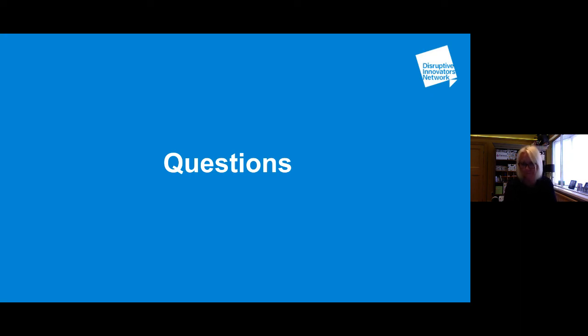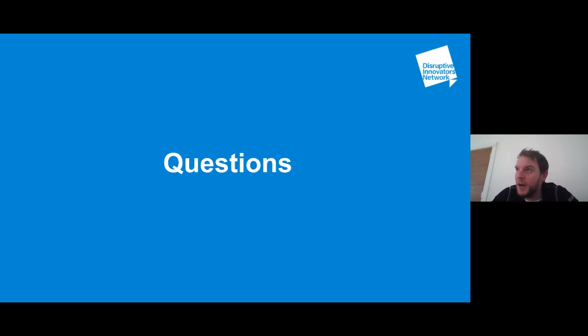Yeah, there's a couple of key points in there. There was one I've just answered to Darren that was about connectivity on a rollout. A lot of the gateways that we use have got SIM cards in, so if you don't have hardwired connectivity, there are options to use the mobile network, because a lot of the data is quite lightweight anyway. When you're doing things like temperature, you don't want to be taking that every 30 seconds because it doesn't change over a 30-second period. So temperature is something you can almost do once every 10, 15, 20 minutes, for example. It doesn't necessarily generate a lot of data, so it works quite well over a SIM card. It depends on what the sensor is actually doing.